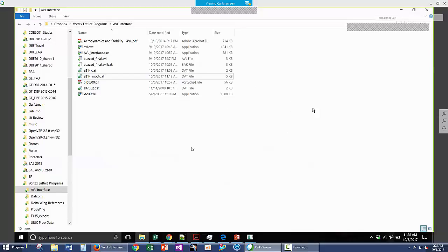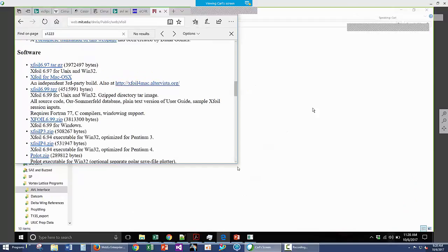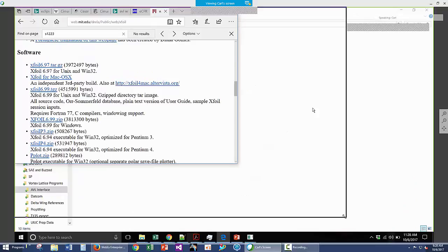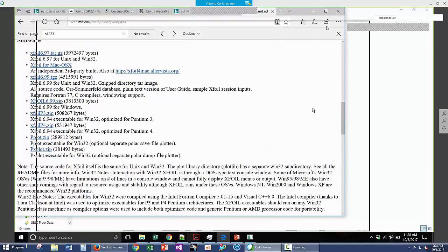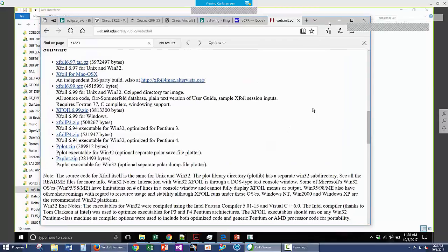Right, so there are multiple methods to do this kind of analysis, and XFLR5 is doing a lot of the same things, or can do many of the same things, but there are particular things that AVL is going to do significantly better, and I encourage you to use that in terms of looking at your stability and the sizing, and we'll go through the particular analysis.